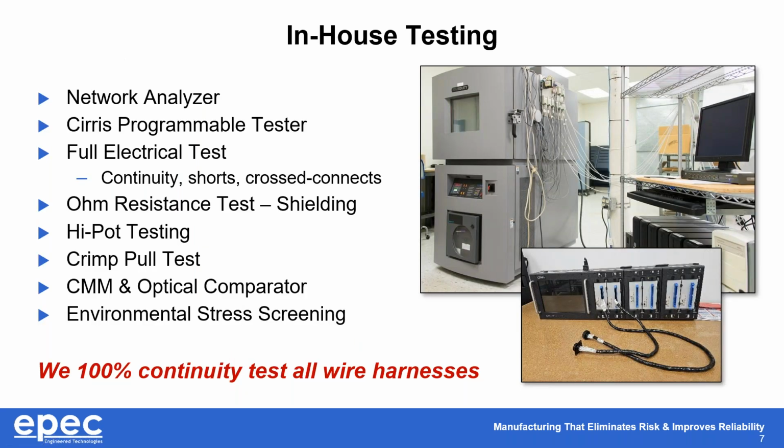Specific to our test capabilities, 100% of our wire harnesses go through continuity test. As we all know, these wire harnesses are dumb devices, and the majority of them don't have any circuitry in them other than just wires and some crimps. With those, a simple continuity test is more than sufficient. For an application where we need to test high voltage limits or maybe do some kind of functionality testing, we do have advanced electrical test capabilities and can develop our own electrical test fixtures that can do exactly what you need to be compliant with your project.